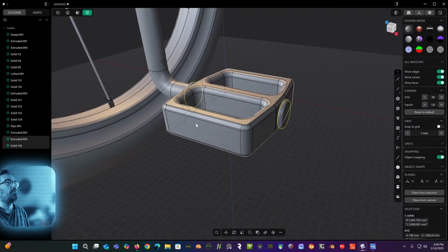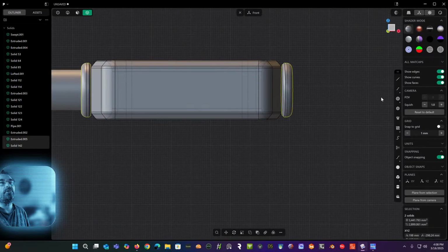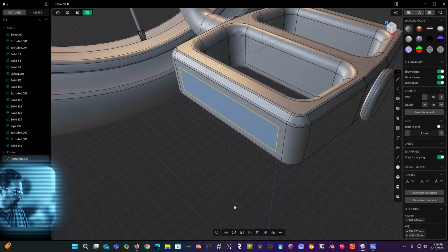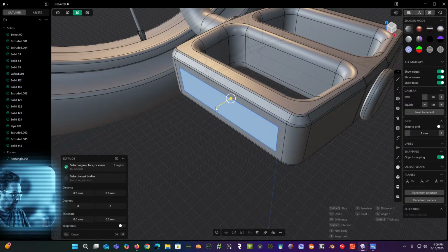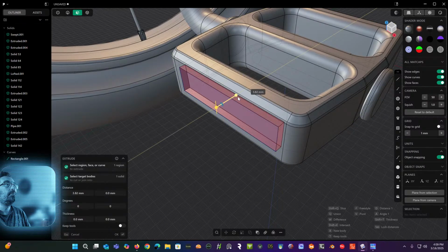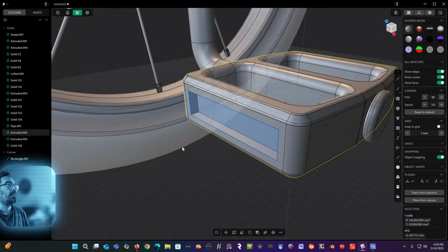Now we probably should put our little reflectors around this. This is pretty simple to do. I'm just going to grab probably a central rectangle, go to the middle, pull this to about, well, maybe here. And then we'll do a Boolean. I just grab this surface, go W, hit the pedal, pull this back into it, however far it needs to be, right click, and you're done.